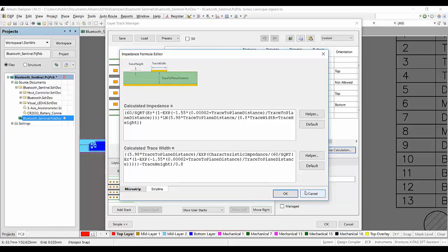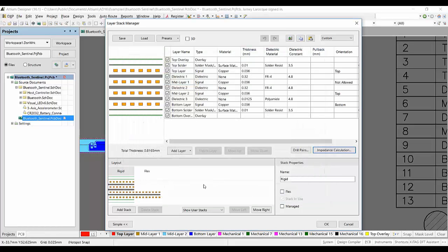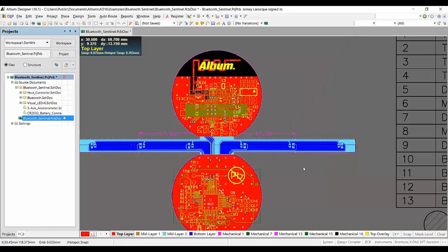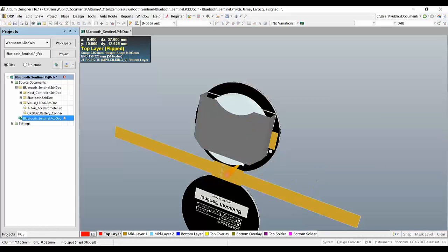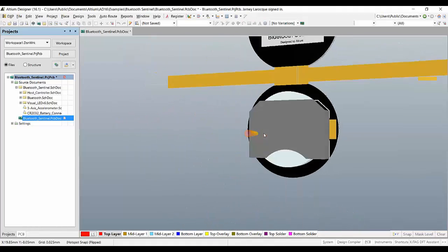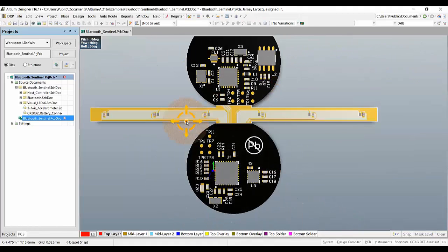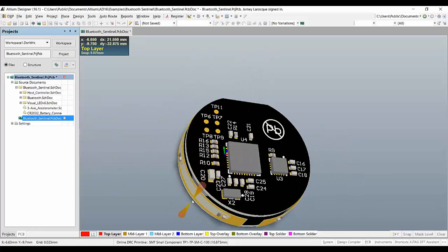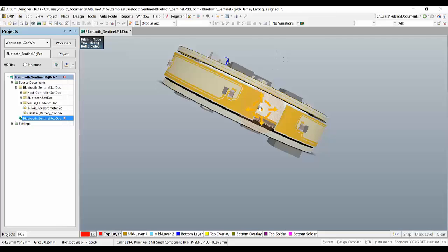Altium supports rigid flex design, and it is as simple as defining a new layer stack within the Layer Stack Manager. Define a master set of layers that includes all layers needed in the rigid flex design. Define the different rigid and flexible zones where each substack is applied, and generate detailed output fabrication and documentation files needed to fabricate the rigid flex PCB.